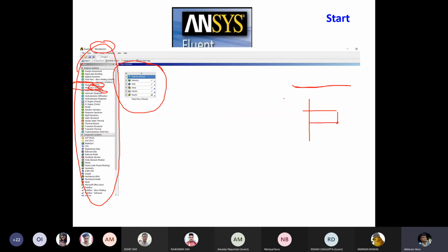Now if that is done, you go to the next stage, that is the meshing part. So you need to mesh it. Mesh means, in that one dimensional heat conduction problem I divided it into 10 points. In this kind of fin, if it is 2D, you can take XY lines so that the entire domain can be divided into a number of points.